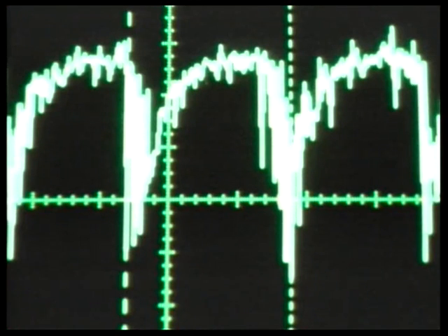So instead of sharing the crystal between two or doing weird stuff like that, you can do power analysis on the board. Okay, so in this case, we're trying to find the instant in time at which a clock edge strikes. And here are some clock edges coming out of the VCC pin of the chip. If you remove the bypass capacitor, the chip still functions. But whenever a clock edge hits, that's when the chip is doing actual calculations, the voltage falls.